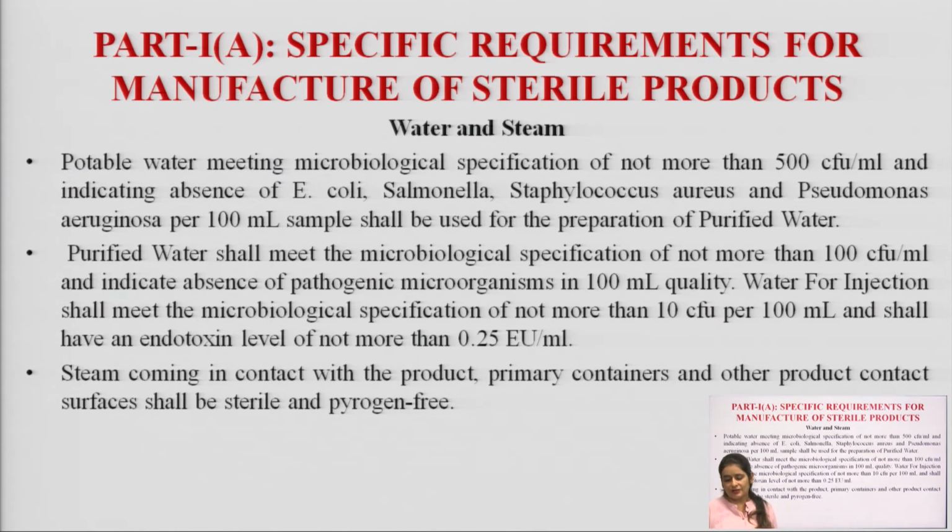Water for injection should be prepared according to the pharmacopoeial specification. Water for injection shall meet the microbiological specification of not more than 10 CFU per 100 ml and shall have an endotoxin level of not more than 0.25 endotoxin unit per ml.